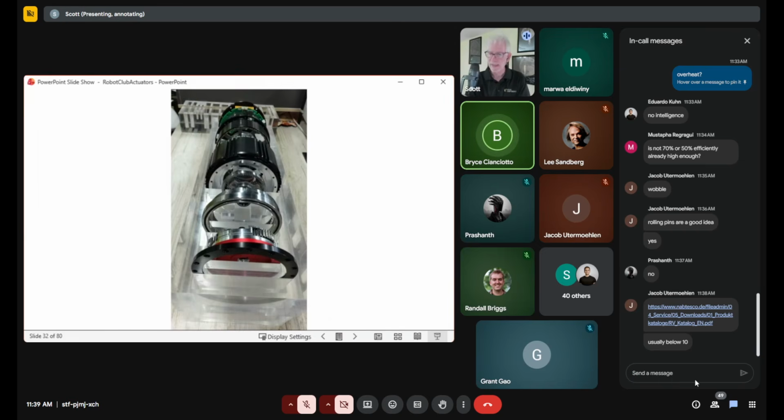As in, it's usually like a 10 to 1. Usually below 10. They will say gear ratio below 10. Others will say you can kind of get up to 20 and maybe get away with it. There's pretty much consensus that once you're above 50, it's not QDD. It just won't work out that way. But it's sort of like, we don't really know where that frontier is. The assumption is it's probably under 20. It might be a little bit higher, but most people prefer to not play above 10. If you can stay down there, you might be able to do it. That might change as we go along. So in many cases, if you need the higher torque, you may have no choice but to do that.